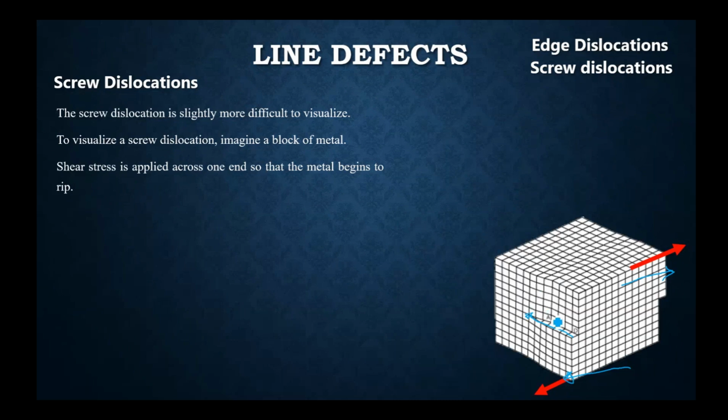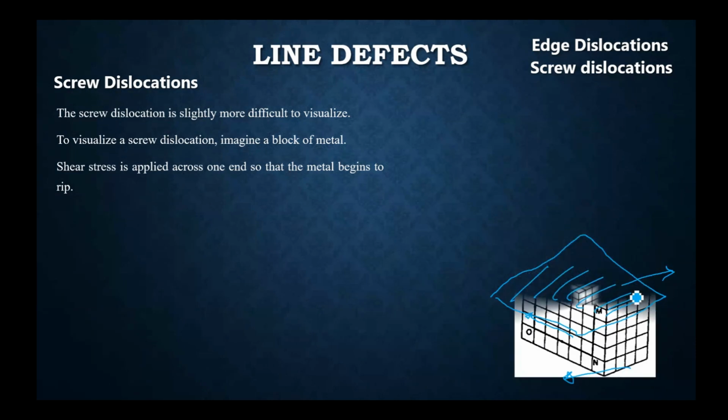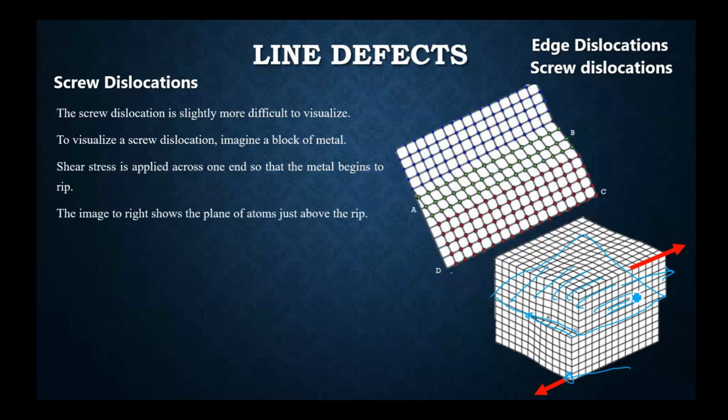And when we looked into the plane that is essentially this plane, the plane which is ripping apart the top surface of it, it appears that these red atoms are the atoms that have moved one atomic distance. The blue atoms are the atoms that are still situated at their original position, and the green atoms are in the process of moving towards one lattice step.